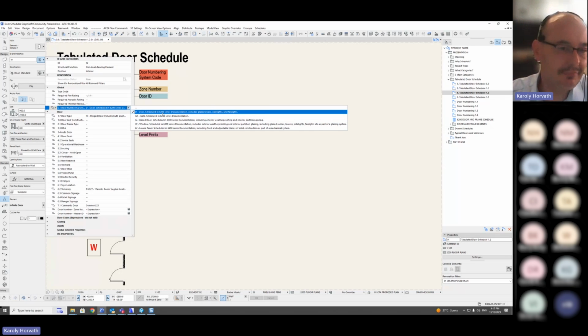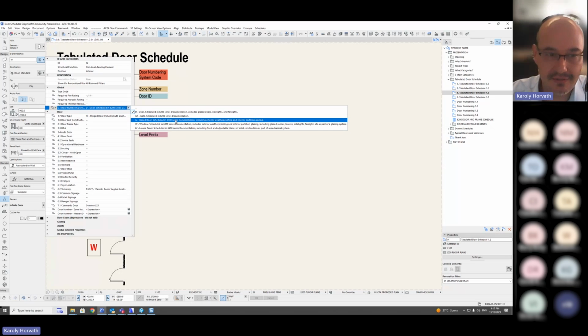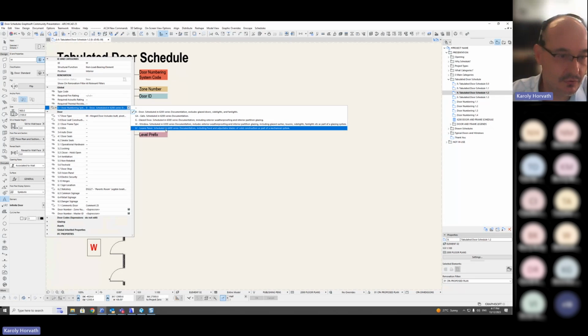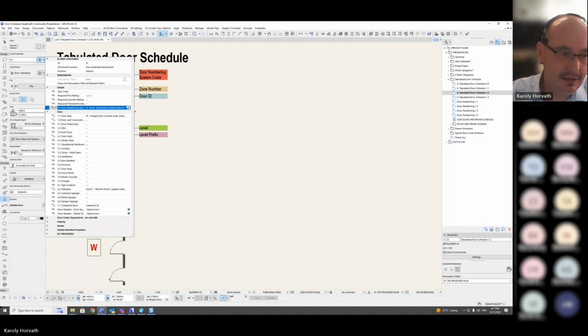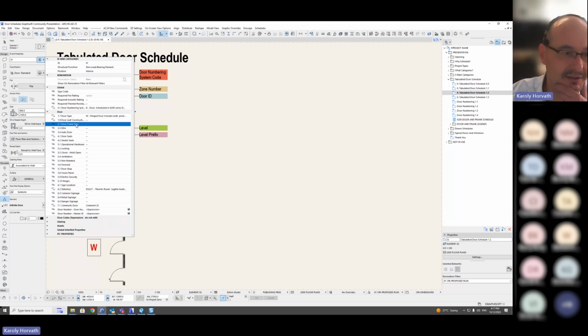As you see, in this case, we do have the doors that are the 6200 series, and then we have gates that will still be on the same series, but in a separate sheet. Then we have glazed doors and windows and louvers separated into different schedules. And then we have all these other properties of the doors that we can choose, and they are just properties created for each element.